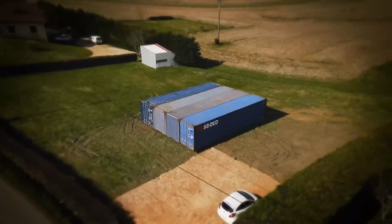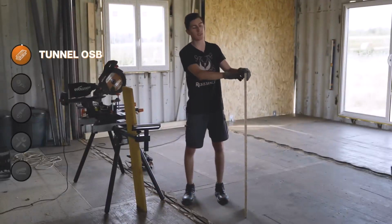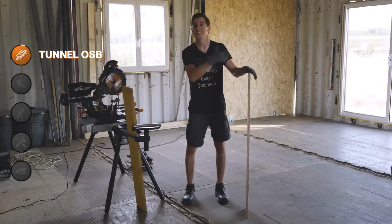To start, we're going to build the tunnel where we'll install our window or our tunnel bay window. And we're going to do that with 18mm oriented strand board because it's strong enough, it's easy to cut, and it used to be cheap before the wood crisis.